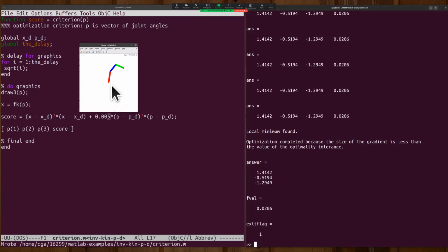What is going on is we're summing up the squares of all three angles, not just the two elbows. And that means that because the shoulder is in a different place with a value of 1.4, it's trying to become smaller. So it's actually being biased to fold over in the wrong way. And that causes the effect on the first elbow to be different from the effect on the second elbow, and thus it's asymmetric.